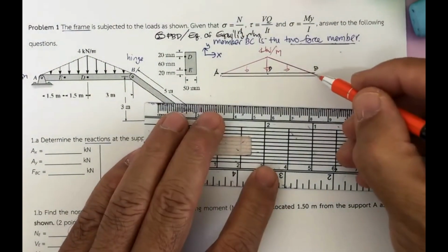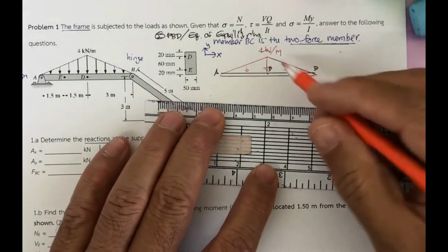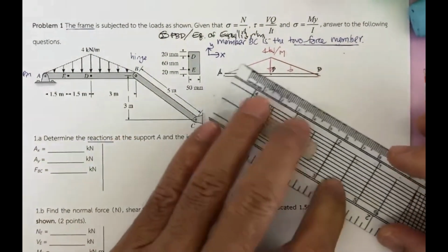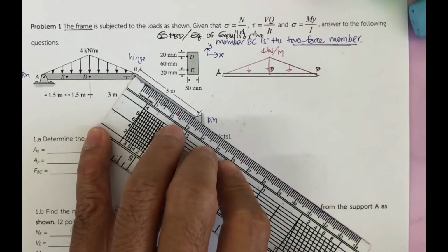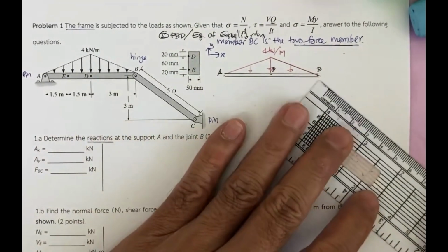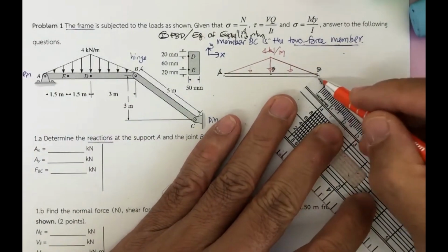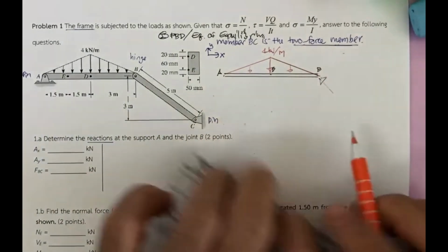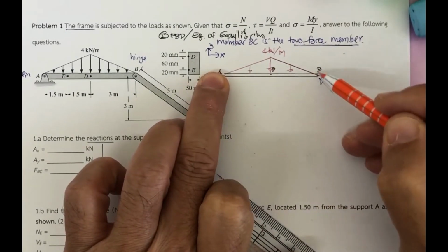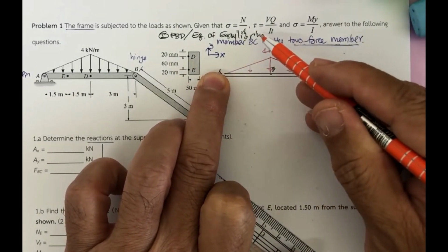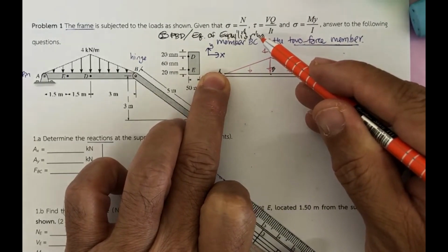And the beam ADB under the application of this force, as we mentioned, the force on member BC is going to resist in this direction to balance the clockwise rotation due to the triangular load. This one is supposed to be in the counterclockwise direction.